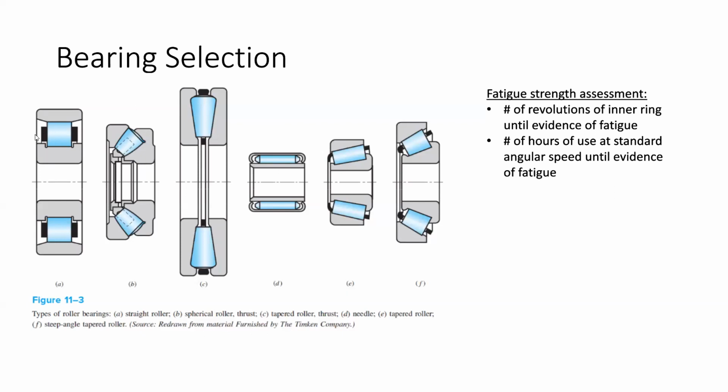So in this cylindrical roller element type, if I were to apply, I guess I should define the different types of load first. In general, there are three types of loads that you want to react with bearings: radial, axial, and moment loads. The radial loads push basically normally to the bearing surface, whether that's originating from the inner ring or the outer ring. Moment loads are where you have a moment applied to either of the rings, and axial loads are where the load is in this direction, in the same axis as the whole.